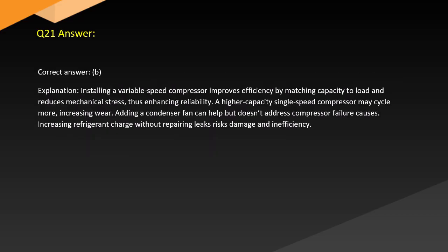Answer. Correct answer: B. Explanation. Installing a variable speed compressor improves efficiency by matching capacity to load and reduces mechanical stress, thus enhancing reliability. A higher capacity single speed compressor may cycle more, increasing wear. Adding a condenser fan can help but doesn't address compressor failure causes. Increasing refrigerant charge without repairing leaks risks damage and inefficiency.